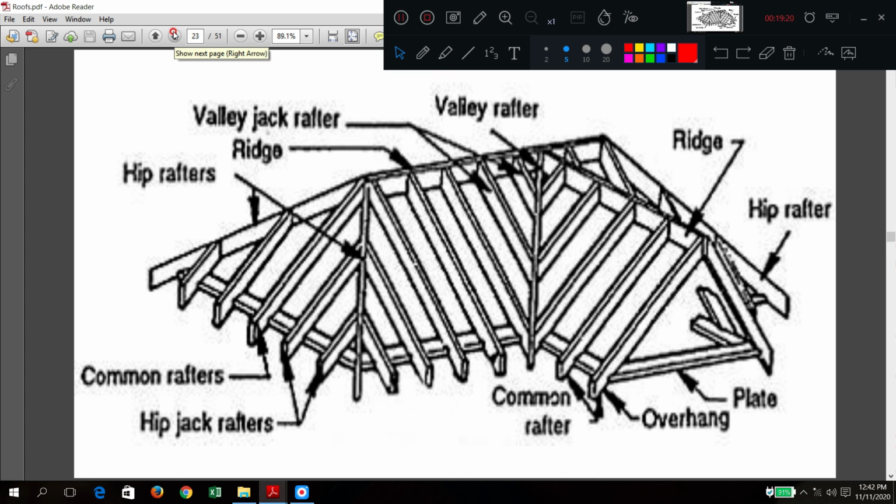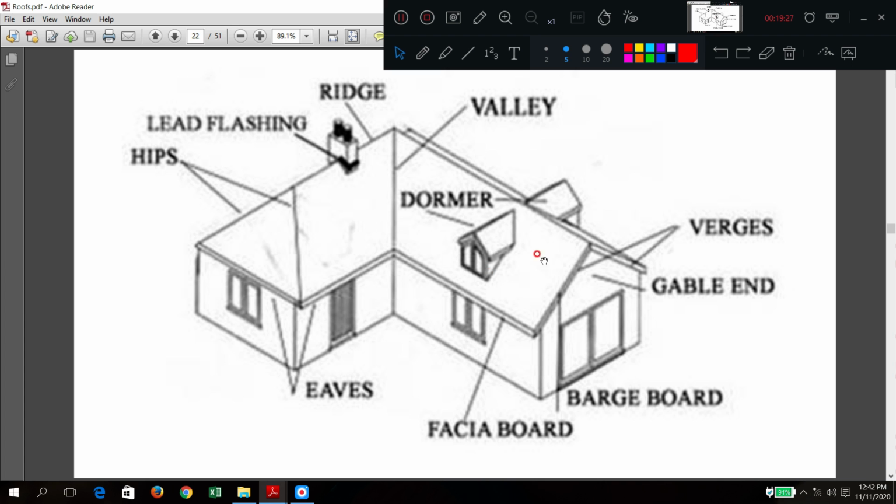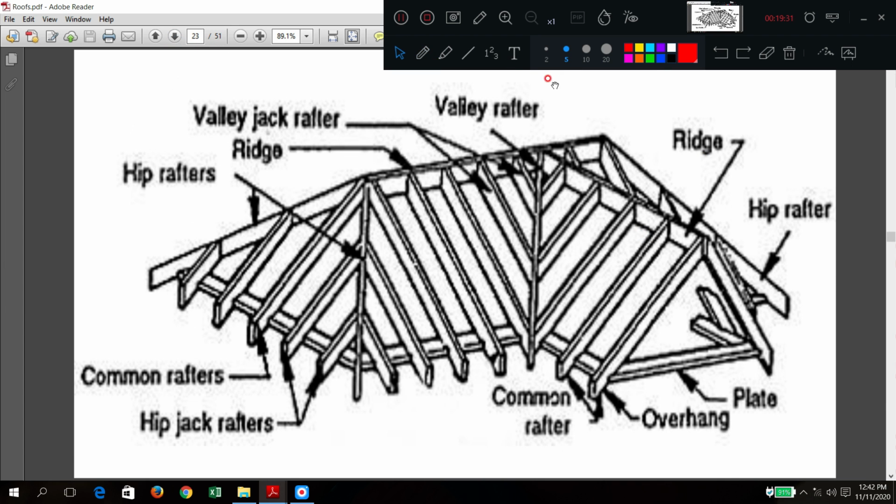Can you see here this one? A typical truss or skeletal. So for the same building, we have drawn the truss. Here you can see where I will mark this one, ridge. This is ridge. Where is that ridge? This line is the ridge. It is going like this, it is also going like this. This is the ridge. Where is the common rafter? That is why they have marked a ridge. Where are the rafters? All these are rafters. I have shown, no, this is inside.